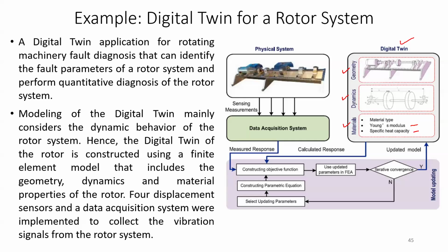So we use different sensing techniques like displacement sensors and a data acquisition system to collect the vibration signals from this real rotor physical system. These signals are the key inputs for detecting faults.